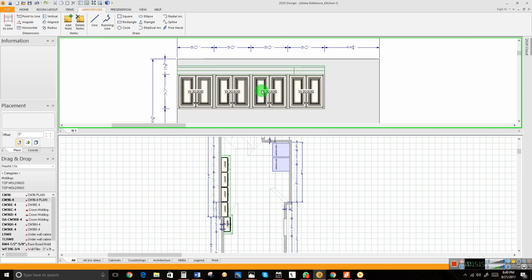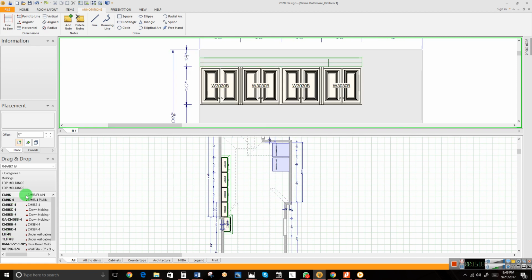So the keynotes for today is, remember, you can drag and drop the best way on your elevations. To stack a molding, place the bottom molding first, then place the next molding on top of the next one. But remember to set your EO height offset, or you could pull right click down to determine your height. But you have to do that every time you open the file. And also, if you want to modify your molding, always remember to adjust the parent molding. It automatically pulls the rest of the molding together.